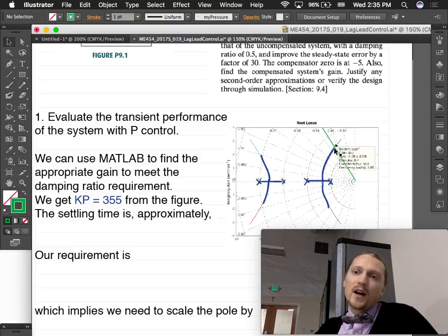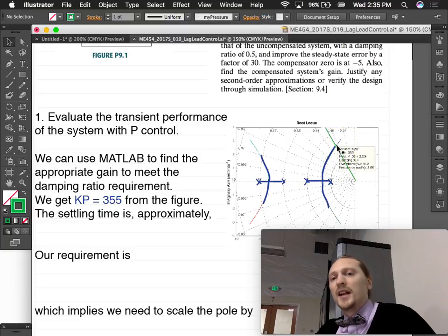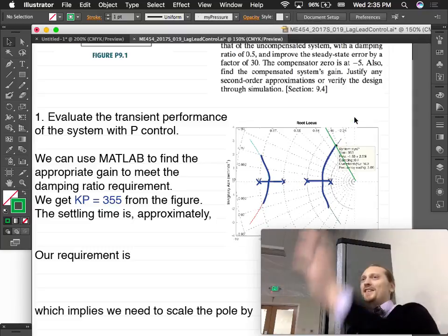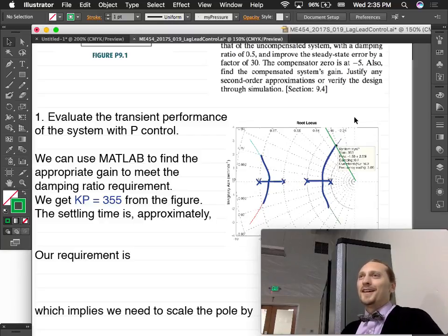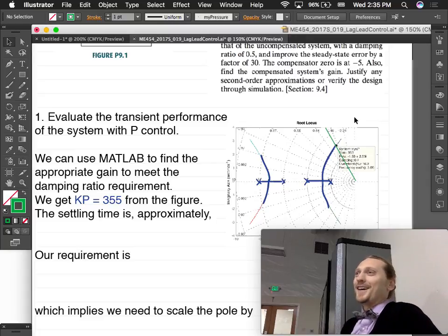And we would say, what does the gain need to be to get on that line? I guess it's more like that. What does my gain need to be to get on that line? I would choose my gain, and then I would say, okay, on to the steady state. I don't even need to do a lead controller because I don't have to get it. Apparently, time is of no object in our design. But it actually is. We want to be a half second faster than whatever we can do with proportional control. So, all right, we're definitely going to need to do a lead controller.